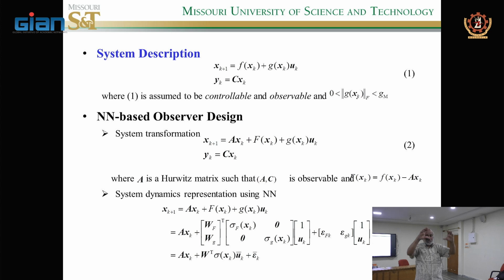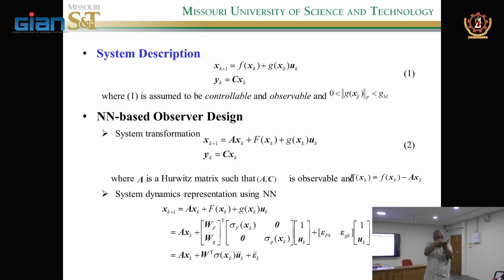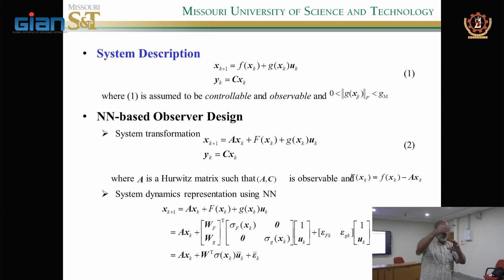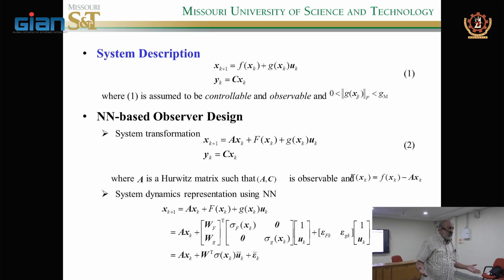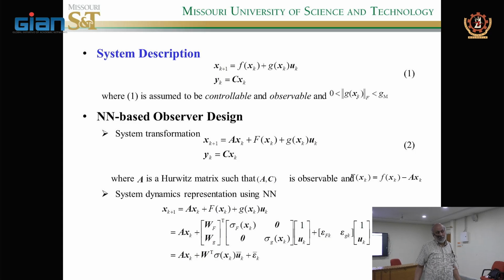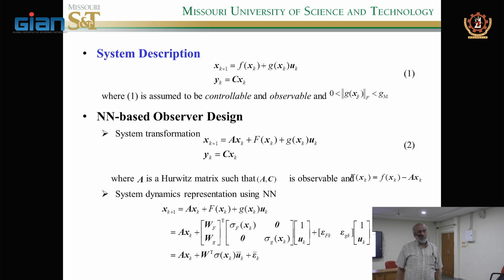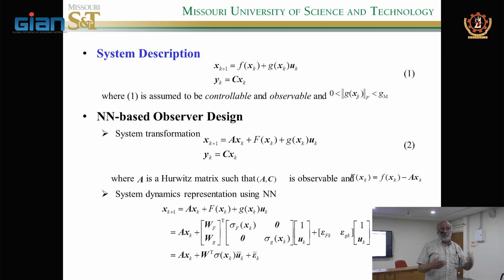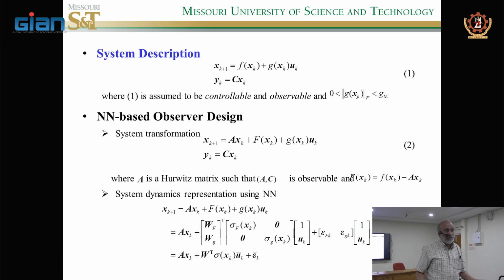So the same thing, that physical system is like a black box. The states are inside the system. You're only seeing the outputs as they project out, and through the outputs you're watching what's going on inside, all the states, what's cooking inside. So if your outputs are not in the right location, that means they're blocking the view of the states. Practically, that's what it means. The only way you can fix that is by changing the location of the sensors or the type of sensor. Sometimes a particular sensor may not give you that, so that's what you need to do.